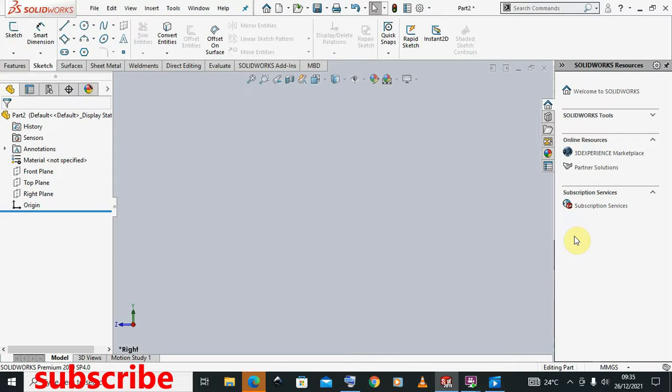So in this tutorial, we are going to be looking at the slots, how to sketch slots, and the different methods under which you can make the slots. So we have a straight slot, we have a center point straight slot, 3-point arc slot, then center point arc slot.